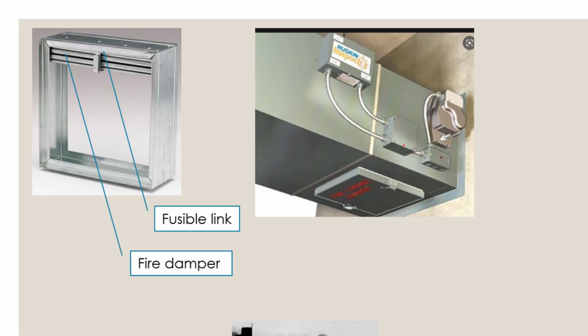So once the fire damper closes, somebody can open up this access door by moving these clips, sliding this panel out, and then they could go in and reload this spring mechanism here and then put another fusible link in place.